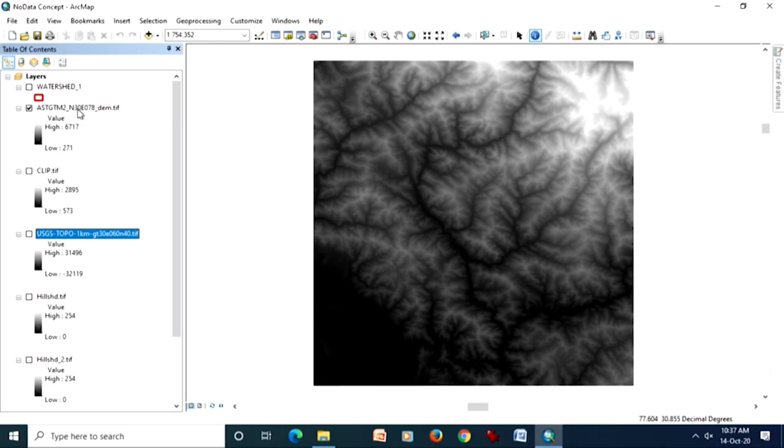It says north 30, that means latitude wise, this corner, the bottom left coordinate, is north 30, that is latitude, and E for longitude of the eastern hemisphere. So E078 means 78. So this is always addressed to the bottom left corner.